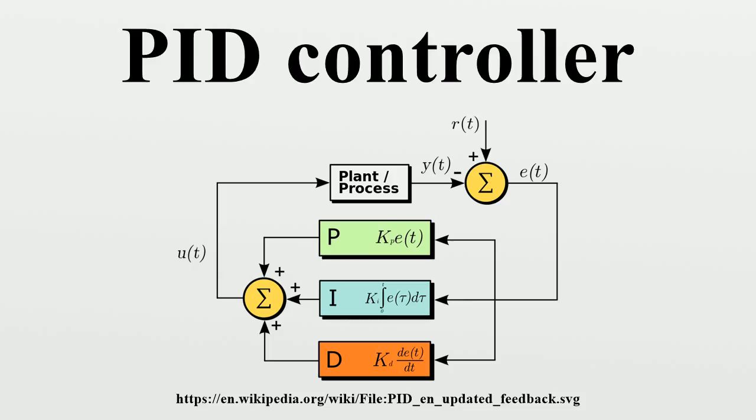As a PID controller relies only on the measured process variable, not on knowledge of the underlying process, it is broadly applicable. By tuning the three parameters of the model, a PID controller can deal with specific process requirements. The response of the controller can be described in terms of its responsiveness to an error, the degree to which the system overshoots a set point, and the degree of any system oscillation.